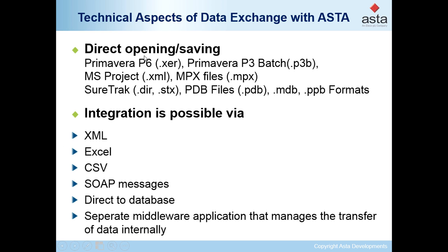In the technical way, if you are already a Primavera P3 user or Microsoft Project user, even if you have files from SureTrack, you can bring your project and open it directly in Asta, or from Asta you can save your projects directly in formats such as P3, P6, and Microsoft Project. But when we have customized integration, it is possible via XML based, Excel, CSV based, or we are directly integrated with the databases.